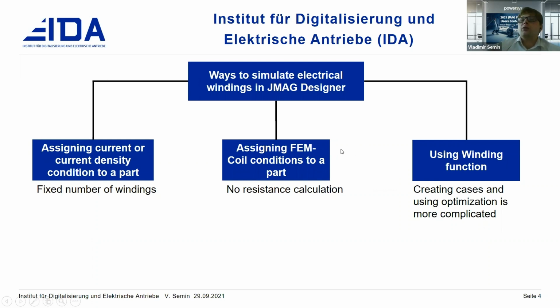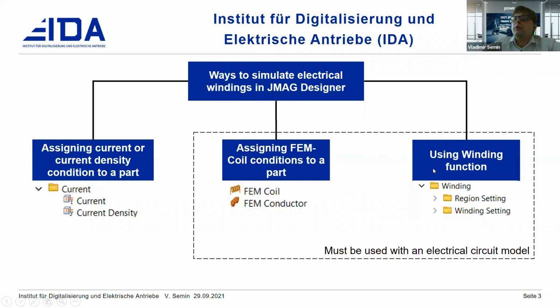And again, I'd like to mention an issue that I had with all these functions: it takes a relatively long time to set all the conditions. For example, in the last case, firstly a circuit has to be created, an electrical model, then the regions have to be set, then the winding has to be set.